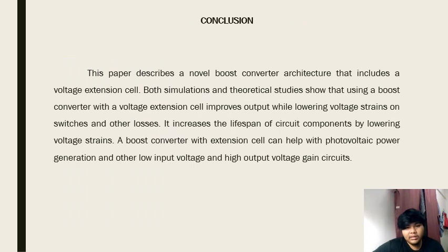To end the presentation, we go to the conclusion. This paper describes a novel boost converter architecture that includes a voltage extension cell. Both simulation and theoretical studies show that using a boost converter with a voltage extension cell improves output while lowering voltage stress on switches and other losses.